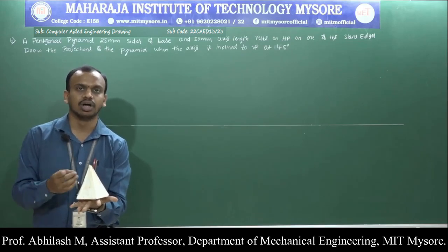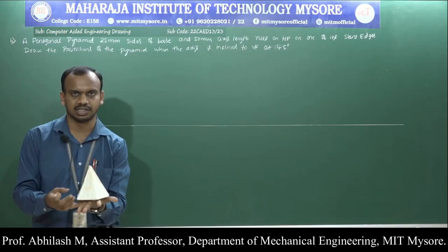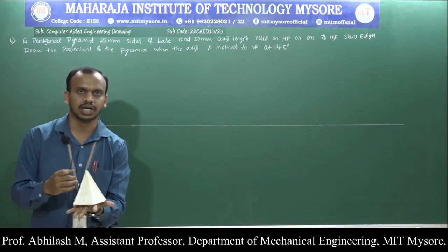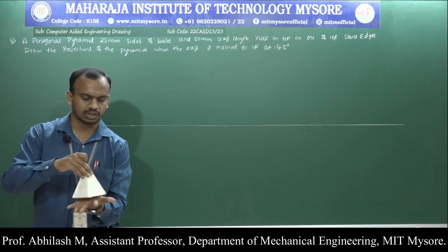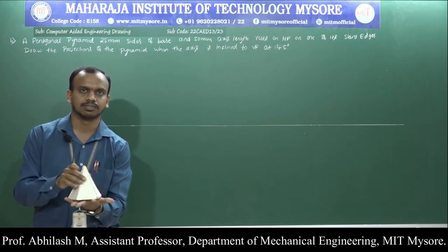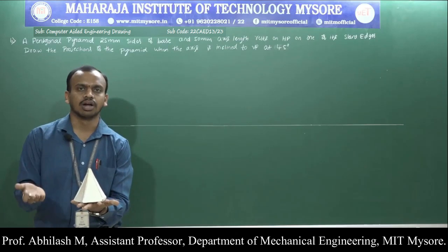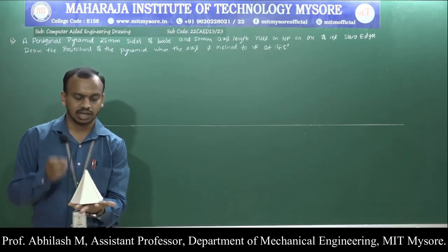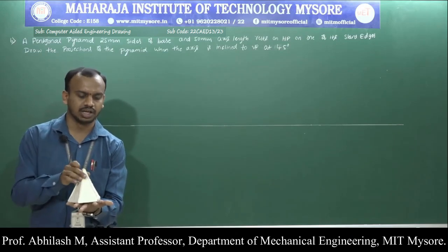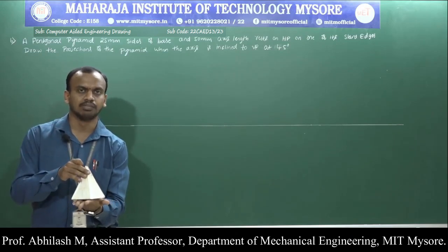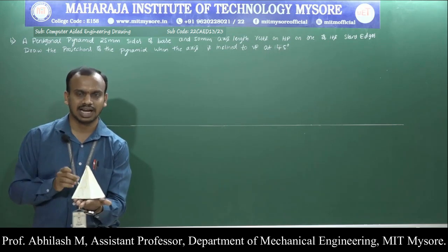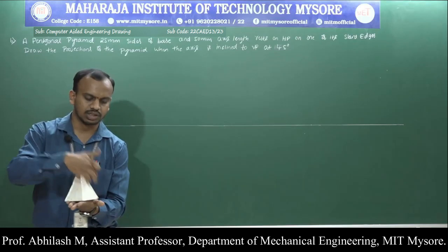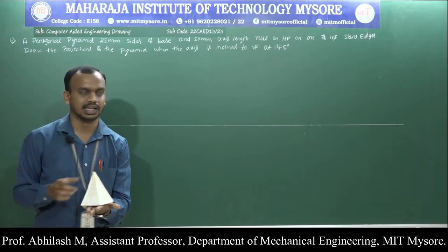If they had mentioned one of the triangular faces rather than the slant edge, if they asked us to rest it on the triangular faces, you are supposed to rest it like this. Basically a corner or the edge condition in the previous cases that you used to solve. Here they are specifically mentioning we are supposed to rest the pentagonal pyramid on one of the slant edges, a corner condition of a pentagon. So this is resting on the slant edge.